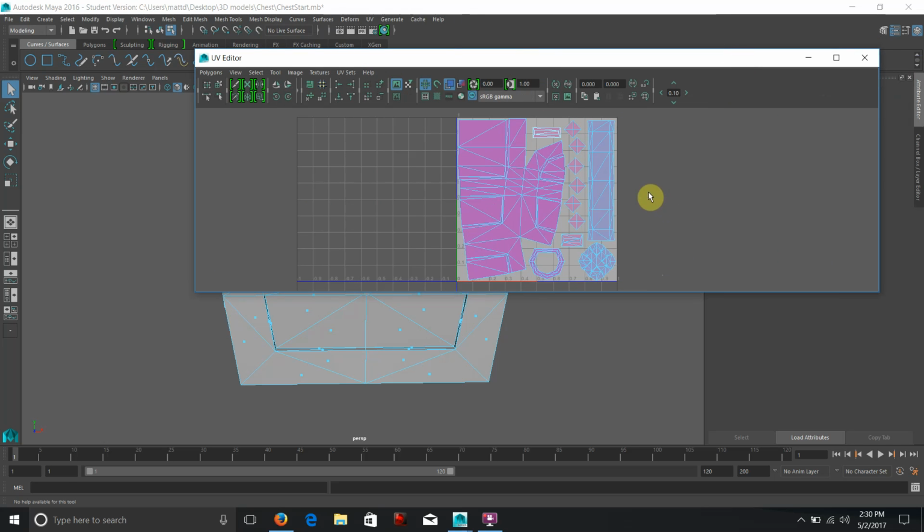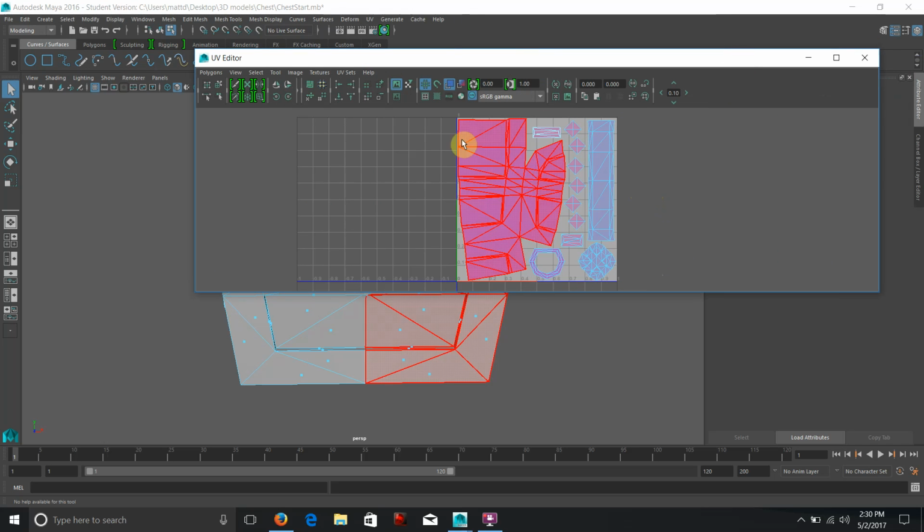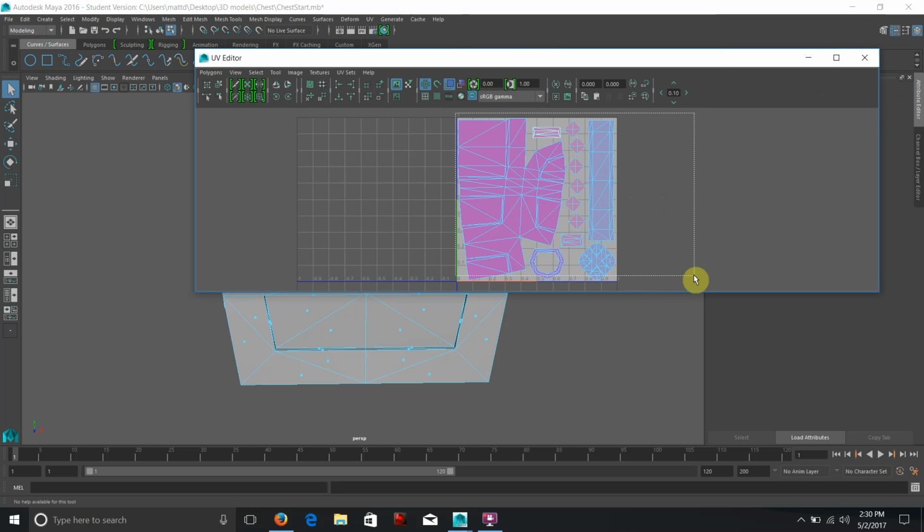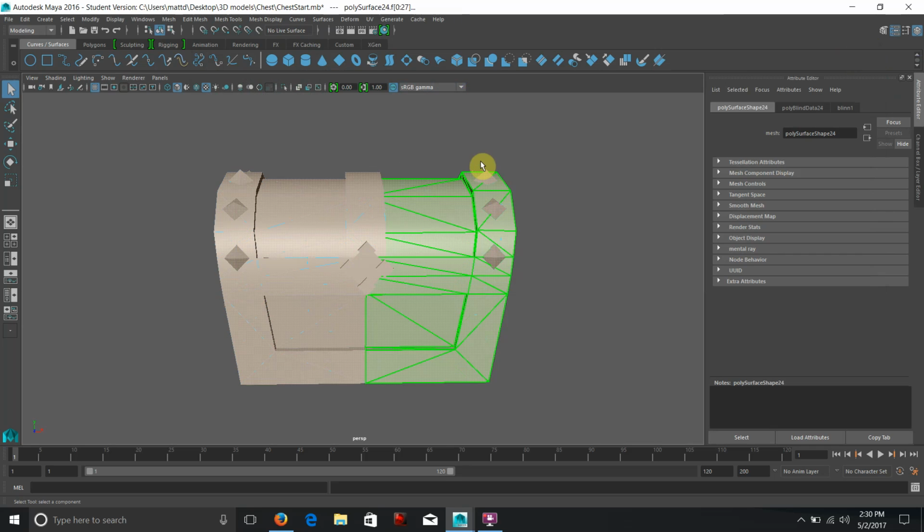It's really important that when you lay out your occlusion map, you also make sure that you lay out your UVs first. There is no occlusion without UVs. Occlusion is actually not based off light. It's based off the distance from one object to another.